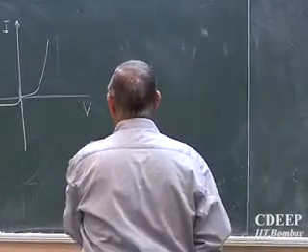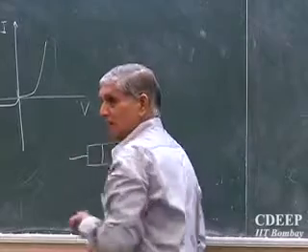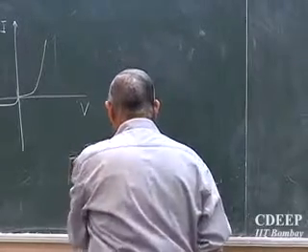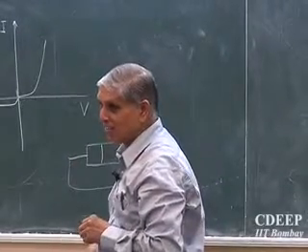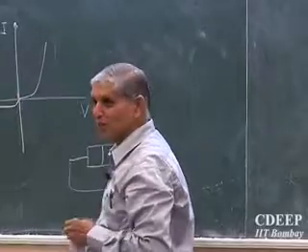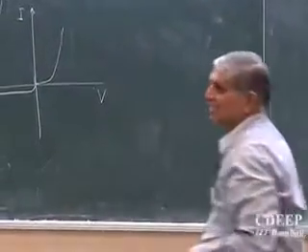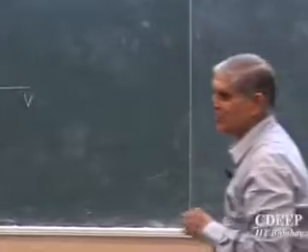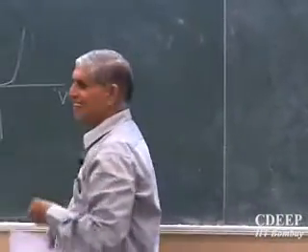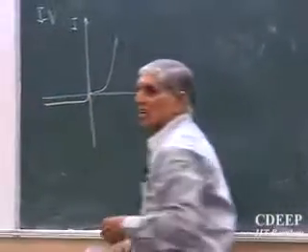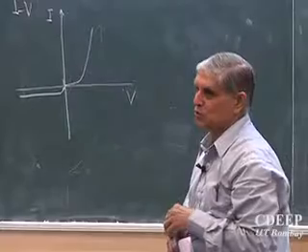Normally in the diode I just did, I said no voltage applied. But even if I short it, which is also V equal to 0 applied, it still gives me zero current. Think of why. Whereas a battery gets discharged, a diode doesn't. Something is there. Think of it. Anyway, the actual current is 0 at 0 bias.